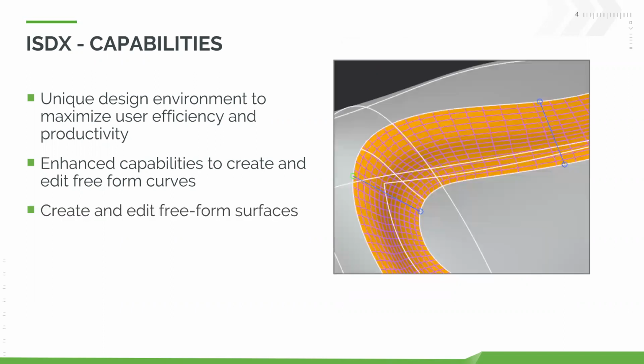And from that point, we made the creation and editing of the surfaces both very flexible and very interactive: boundary, loft, blend surfaces, smart curve and surface, making those connections, making sure that everything that we build out is going to transition how we need it to.